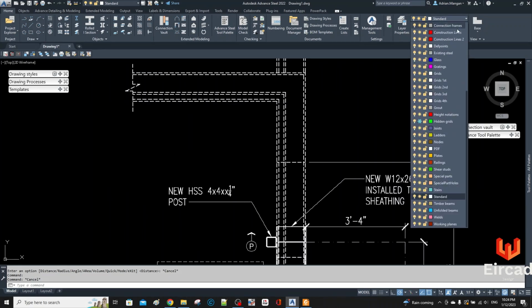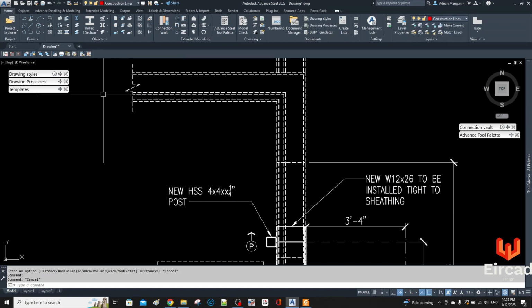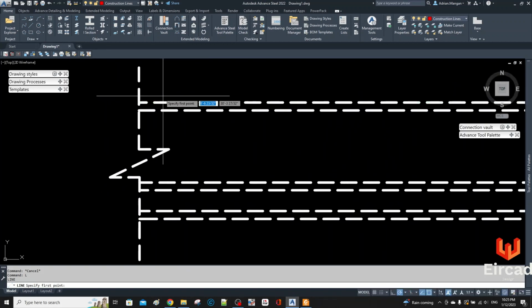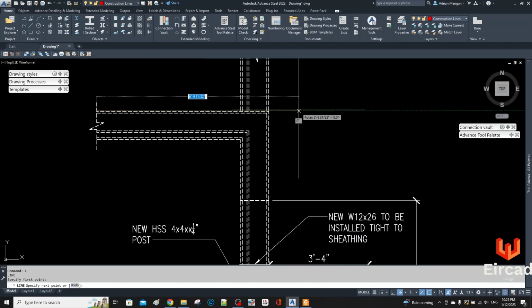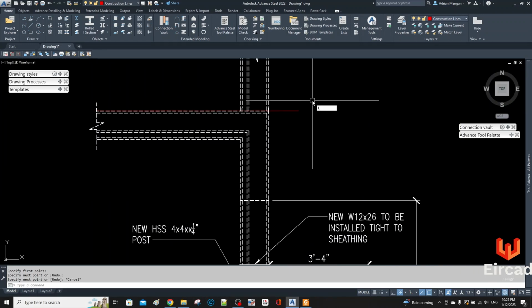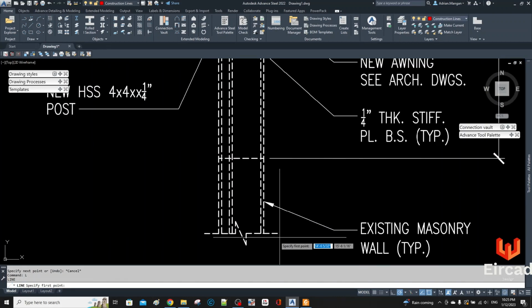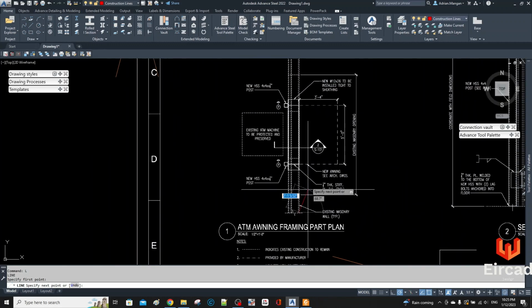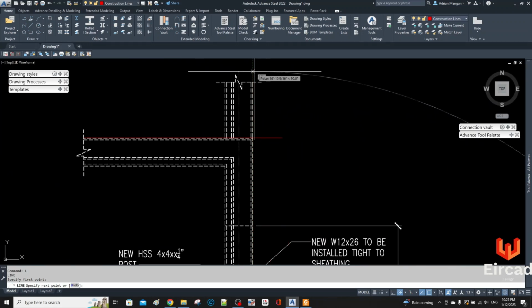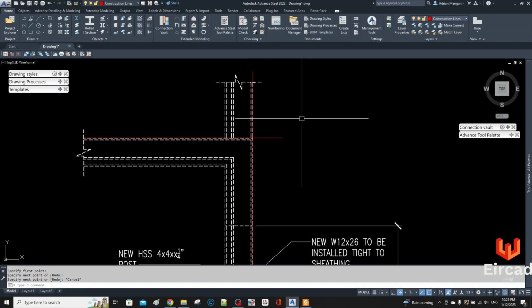So what I'll do is I'll go to a construction line. And it's a small job. Generally, I'll draw lines at 90 degrees. I won't snap the second one. I'll just snap the first one. So I'm going to go out here. I'm going to snap this line. And you can see the way it's gone to 0. And I'll snap that there. And then I'll do the same here. Now, I can fix that afterwards. I'll just fill it that.